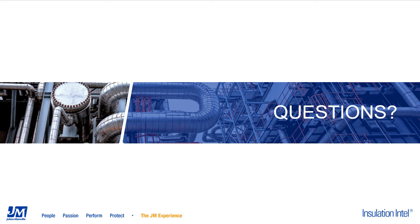Okay. There's also a video of this online if you would like to see how the water-resistant Thermo 1200 reacts to water exposure. You can visit that from our Thermo 1200 page. The next question is also for you, Scott, and that is, does the hydrophobic treatment for insulation also burn off at high temperatures? Yes, it does. It is an organic part of the chemistry of the product, and that hydrophobic feature is going to oxidize and burn off when you get up around and above 600 degrees Fahrenheit.